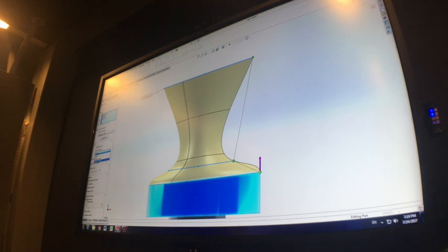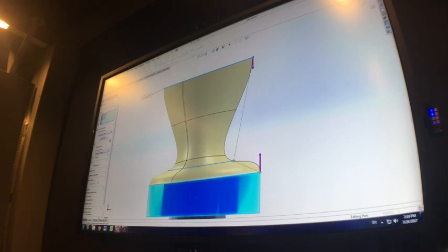Instead, we can use normal to profile. Normal to, okay, like when we select a flat face and we look directly at it, it's straight from that face. So normal to profile means it's going to come straight down and then start curving. Now these values here, you can also adjust them, okay, so you can increase or decrease those points.